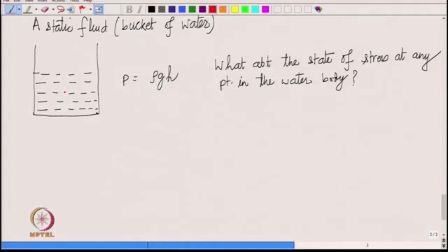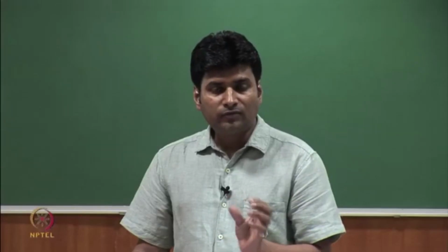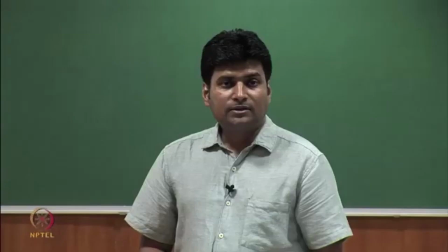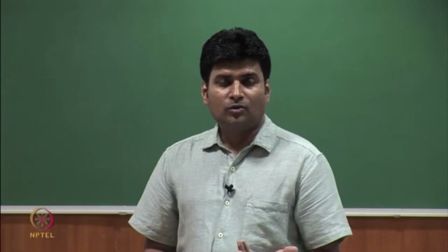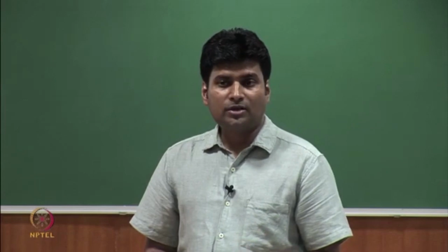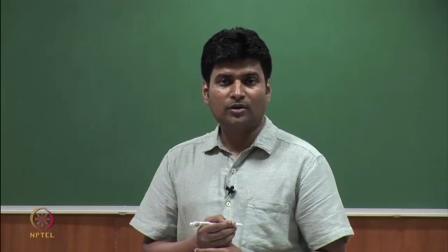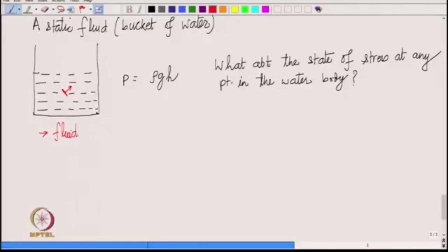Think of any plane at that point, a small infinitesimal plane at that point. Suppose this plane has a normal along some direction. So, what is the traction on that plane? It is the same pressure. Fluid cannot sustain shear when it is in static equilibrium. Okay. So, fluids do not sustain shear.